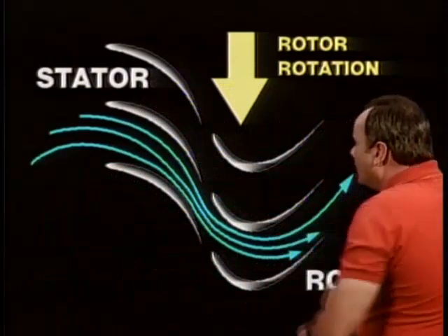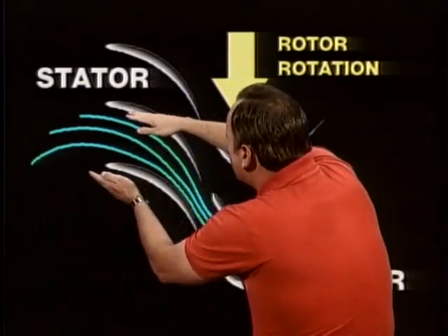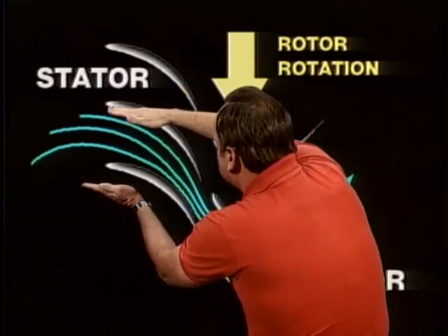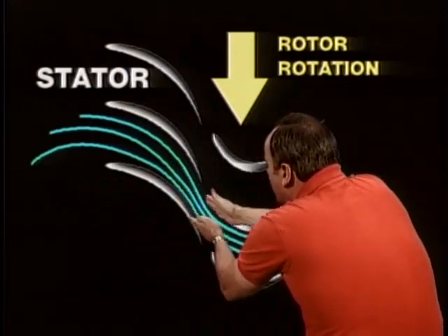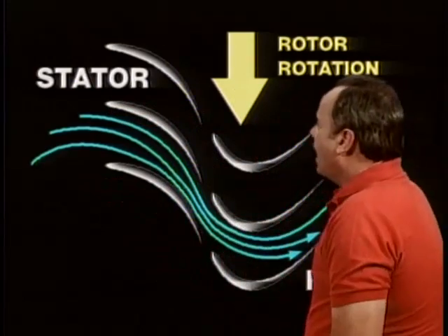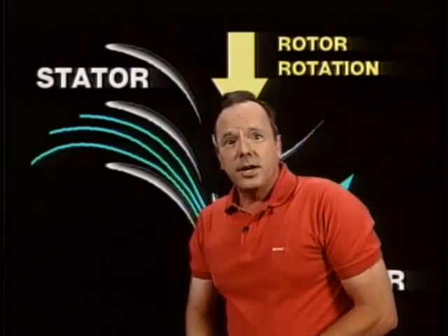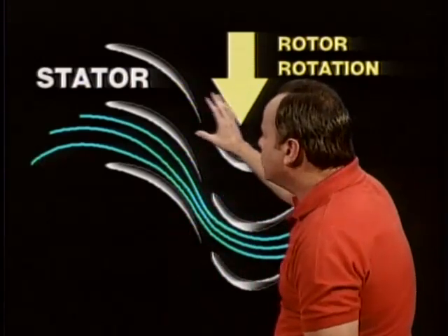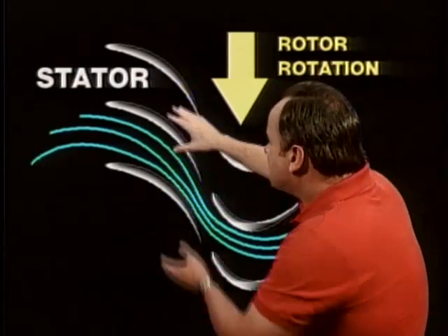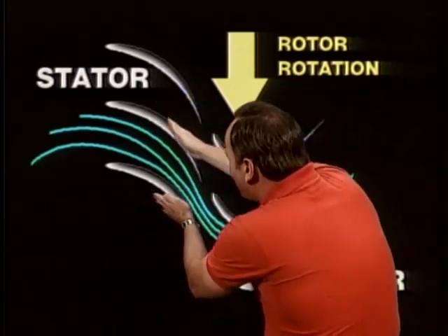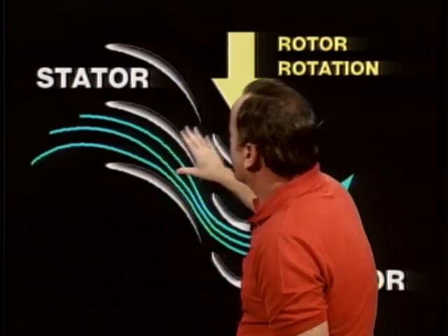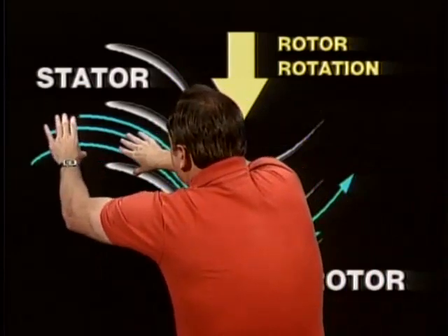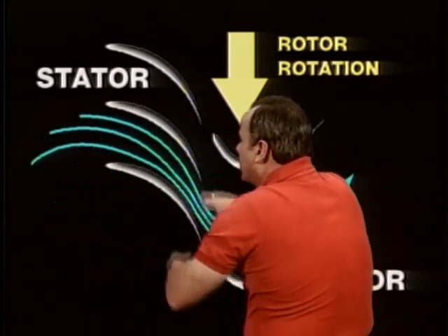So the turbine wheel rotates, that's called the rotor, and the stator is these guide vanes that guide the air into the turbine blades. Now, this stator is often called a nozzle because it directs the air like a nozzle does right into the turbine blades. Now, where does the heat take place in an engine? Well, the highest heat-to-metal contact in the jet engine is in these turbine inlet guide vanes. That's what this stator is called, and this is where things are really hot because the burner can was just right over here, so it's the air coming right out of the burner can.